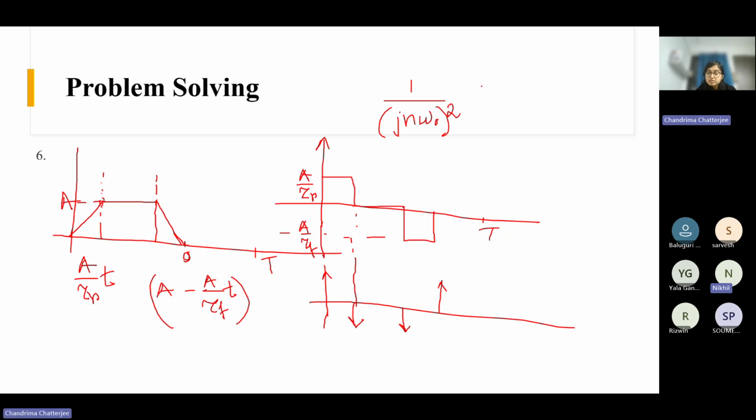On a single board, I have an inverter module. Also, I have one auxiliary supply that powers the auxiliary gate drivers and other things. Both operate at different switching frequency and operating frequency levels. So as a design engineer, we have to take a call: what will be our switching frequency for the power topology? What will be the switching frequency for our auxiliary supply and other things? Because those things will interact with each other, as they are sitting on a single PCB.